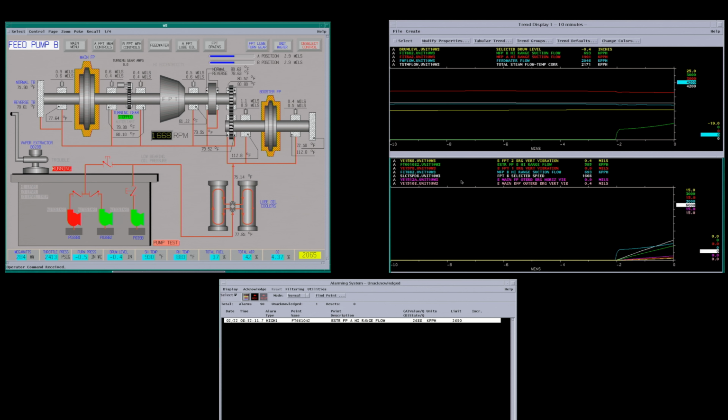Usually the problem with this pump, this runs a little slower speed than the main feed pump, so it will outpump it at certain ranges. There's certain flow ranges where you wouldn't run this thing. It just starves your main pump and will start cavitating. When the pump cavitates, it'll cause a lot of piping movement and a lot of damage. So you want to avoid cavitation on pumps.